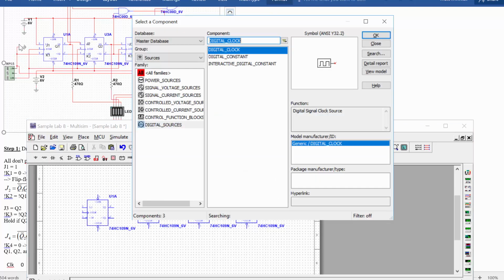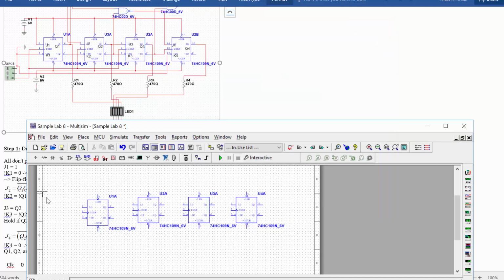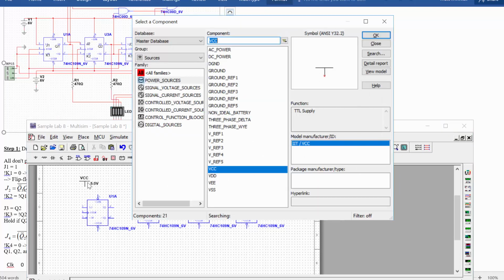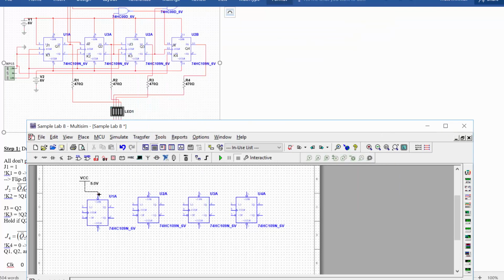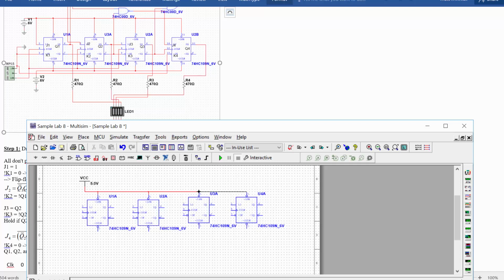Now we can modify what's on the circuit diagram a little bit, so we don't need to have exactly a 6 volts with a ground there. We can put instead just VCC, and this is going to be a global connection there. So we'll go VCC and connect that up to the top. Same thing for these other ones there. So don't reset. Connect it up like that. Yeah, that's good.